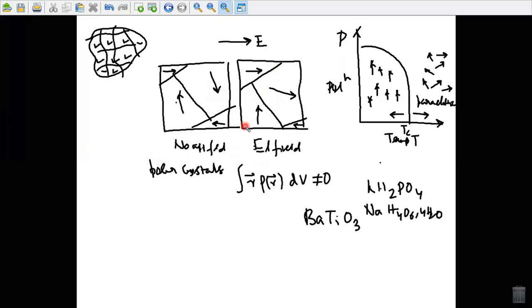When the direction of the field E is reversed, the dipole orientation switches to become aligned with the new field direction. As the strength of the reverse field is increased, PS, that is the spontaneous polarization, will eventually occur with the opposite polarization. As the field alternates, a hysteresis loop is produced. The area contained within the loop is related to the energy required to cause the polarization to switch directions.